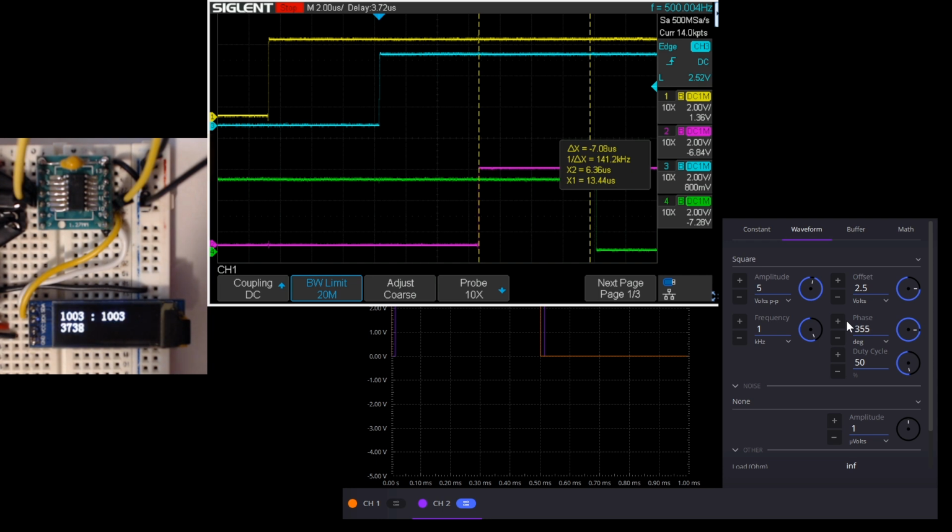And that's because both of these interrupts are having to do all of that context saving. But the second interrupt is actually taking slightly longer, up to about here. And so that makes sense too, because the second interrupt service routine is using a less efficient way to toggle the pin. So this is also what we expect. These measurements are a little bit approximate because of the sensitivity to the cursor placement that I'm doing manually.